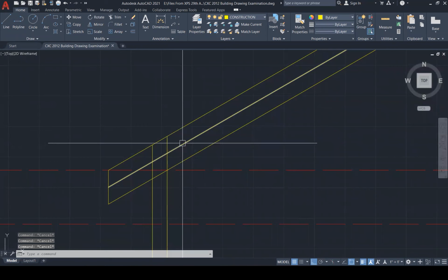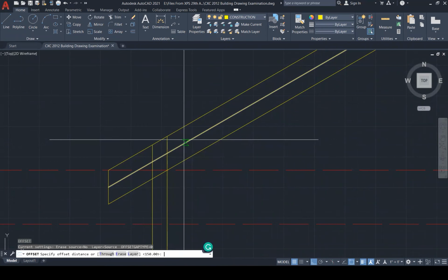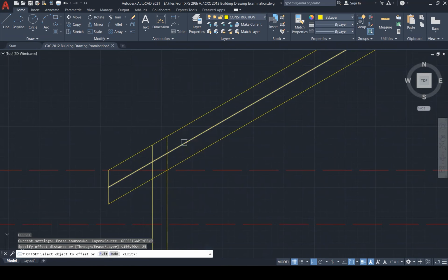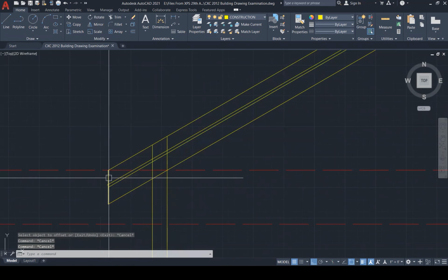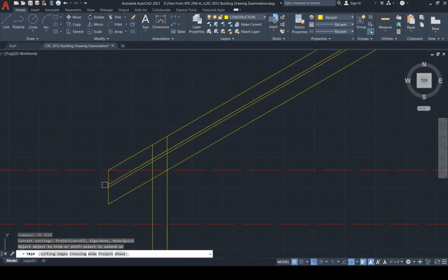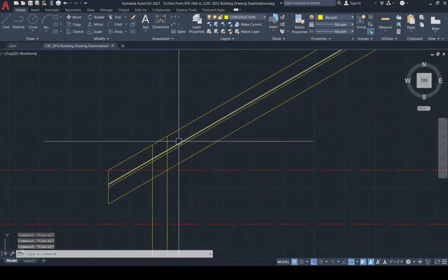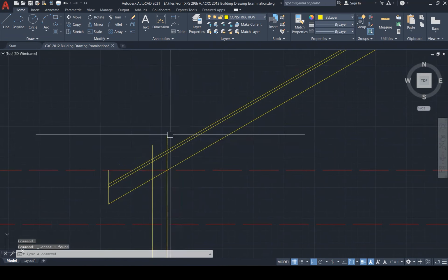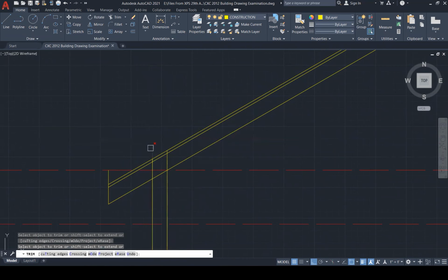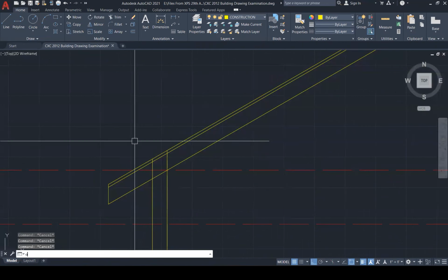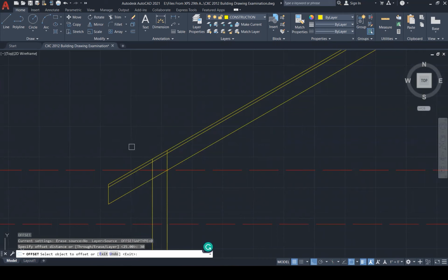Now, I can offset the, I'm going to offset one layer of close boarding over the rafters. And then on top of the close boarding, I'm going to place one layer of battens. So that layer would come in at, let's use the battens at 30 by 30s.